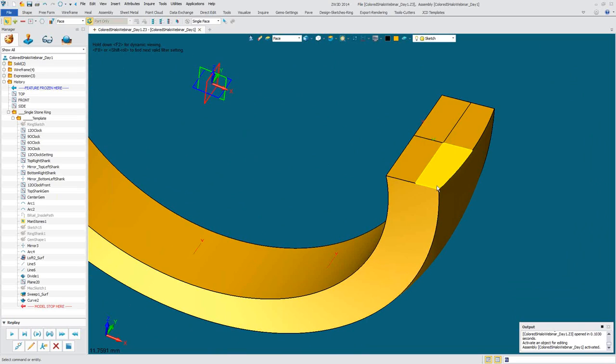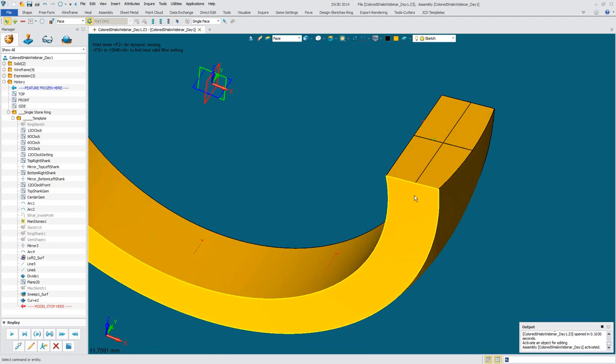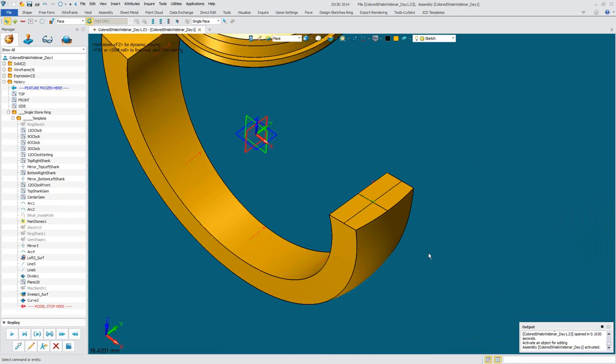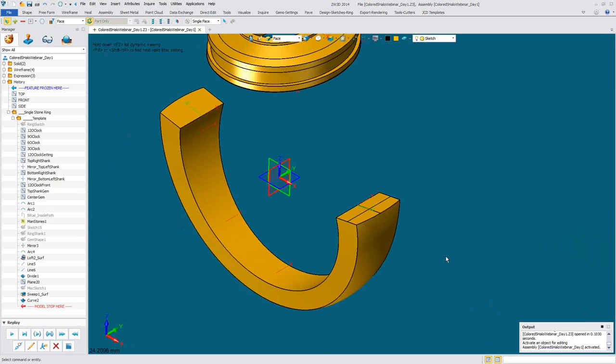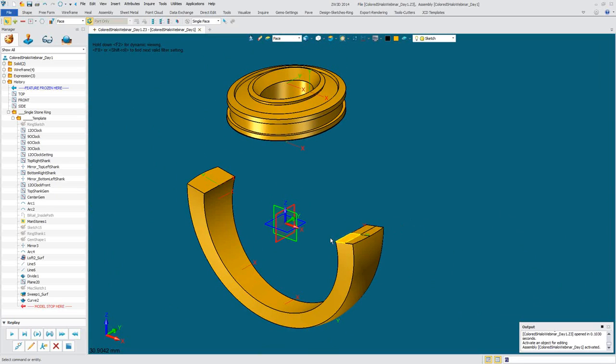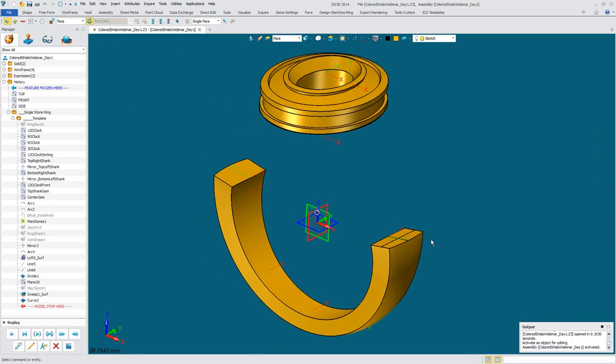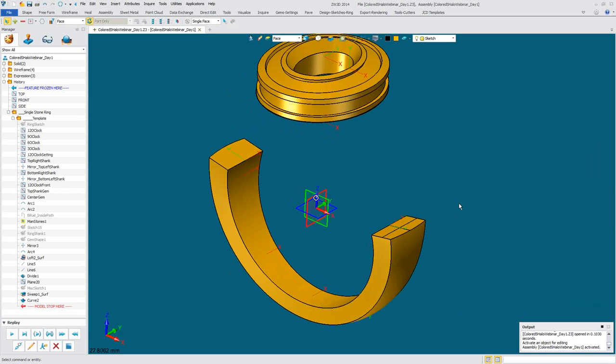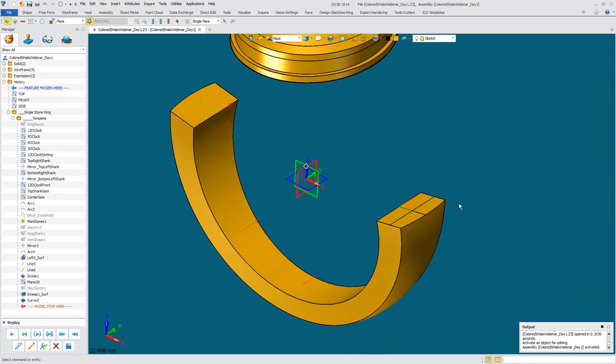Instead of a 2-point line, we put in a spline. With the spline, we can put in an end point, a midpoint, and another end point over here, or even force it to be tangent to this, and we can drag on it and make all sorts of organic shapes. I'll do that in another video so you can see it. Okay, but I just want you to be aware of that. A lot of times I'm building not necessarily for speed. I want to unload information, and you play with it within our given time.